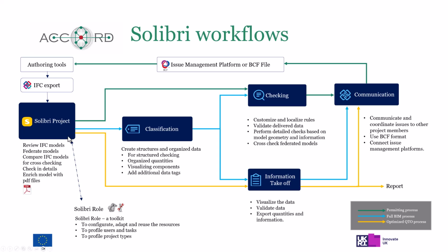The optimized way, as an example on sites, is to get the IFC export and go to the information takeoff, get the quantities out, visualize the situation, and report it to the needing stakeholders, and also communicate to the author if something is found. Of course, some cases require classifications. It's easy to classify and visualize content for a good information takeoff.